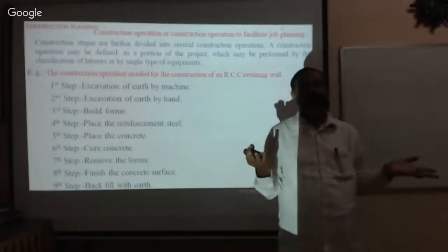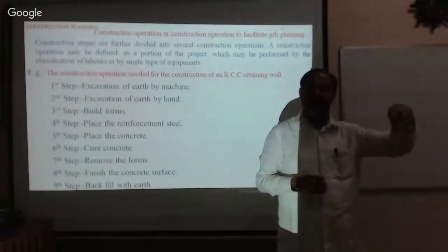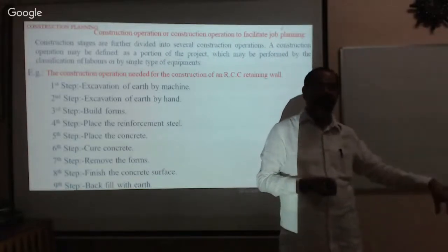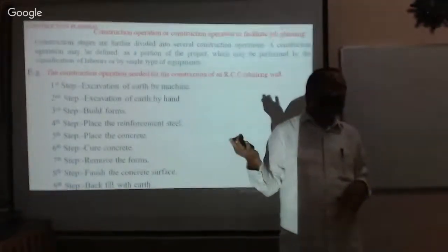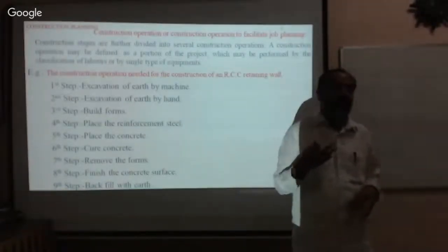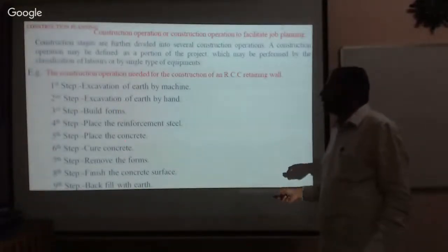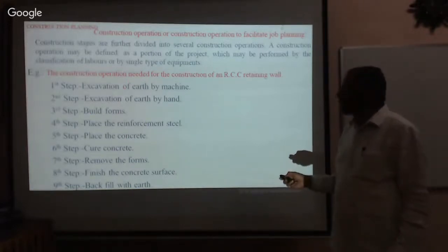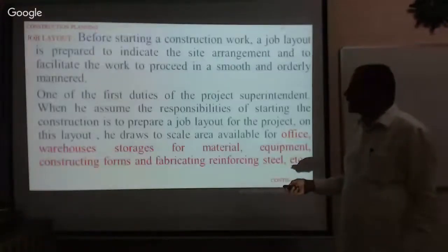In one side of a 2 or 3 acre land, if we investigate the foundation rock depth, in one corner it is 8 meters below, and in another corner there are possibilities it may be 20 meters below. Therefore, we can't estimate it roughly. Be careful while estimating this. These are the steps to be followed in each and every activity, each and every project, that you need to plan at an earlier stage.